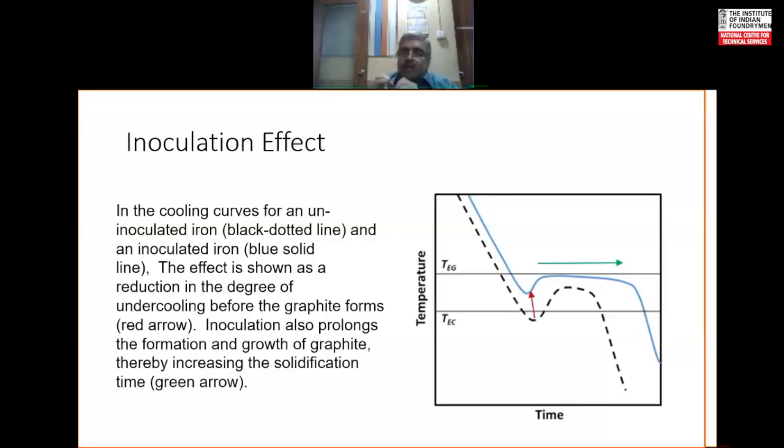So there is a local level of what we call undercooling. You may have a particular temperature which we formally call either the eutectic temperature or melting temperature, but when actual solidification is happening in real life conditions, to ensure that the nuclei are stable, it has to undercool, and that energy is useful for creating the stable nuclei. That is why this phenomenon of undercooling happens.